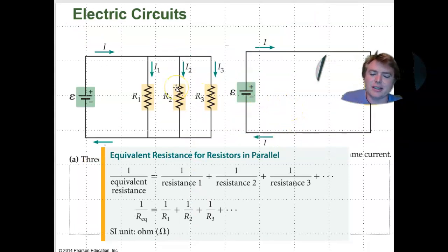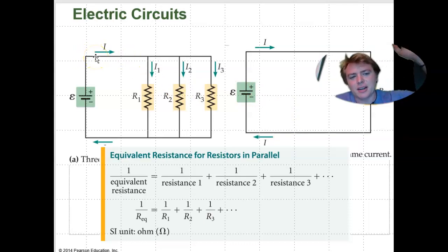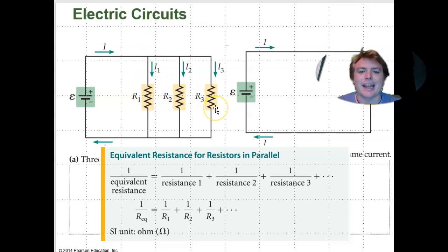Now, when we go to resistors that are in parallel, that is a little bit different. So again, looking at this analogy, you can imagine that I have some reservoir up high, and then I've got a change in height, and each of these is a dam that slows the water but gets some sort of energy out of it as it flows from high to low. If I keep on adding more paths for the water to flow, I'm going to be able to move more water, no matter how much resistance they have, right? I could open a big wide channel. If I add a tiny little sliver on the other side, well, I'm going to be increasing the flow.